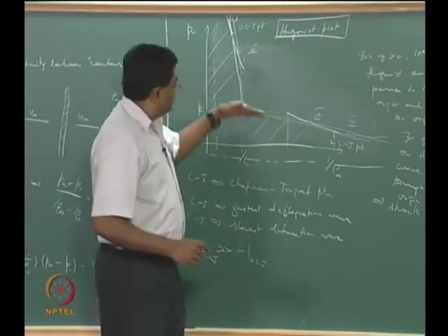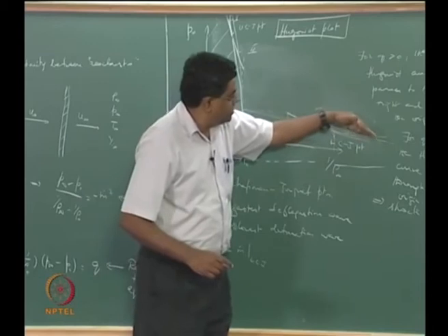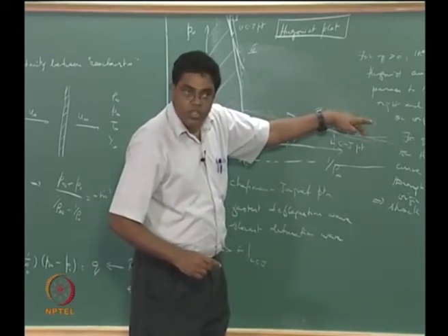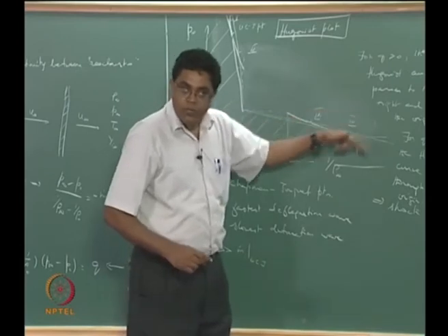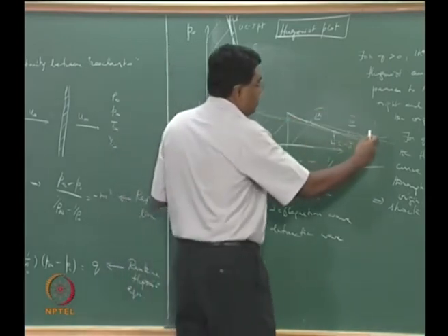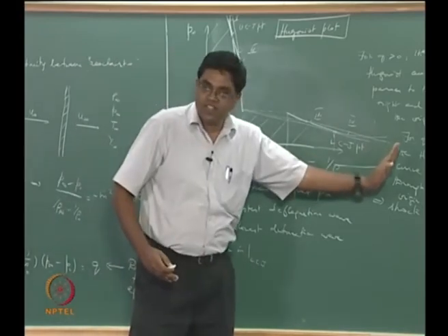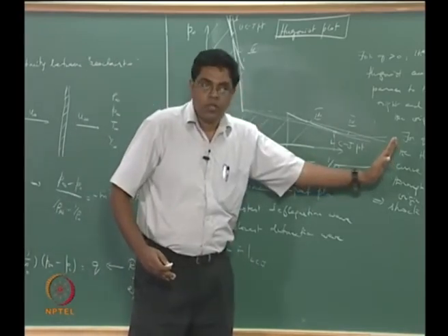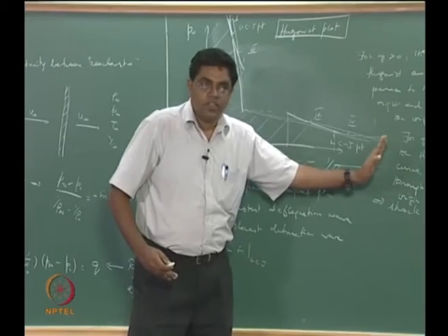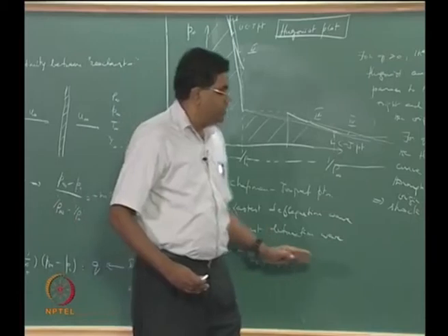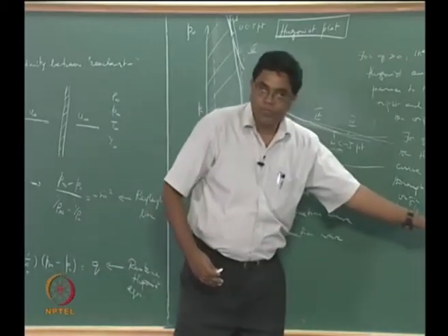But for this low deflagration you still can intersect over there. So this wave is just as slow, but it is actually causing a large decrease in pressure and a correspondingly large decrease in density, right. That is a lot of expansion that is going on, and that is why we want to term it as a strong deflagration, right.